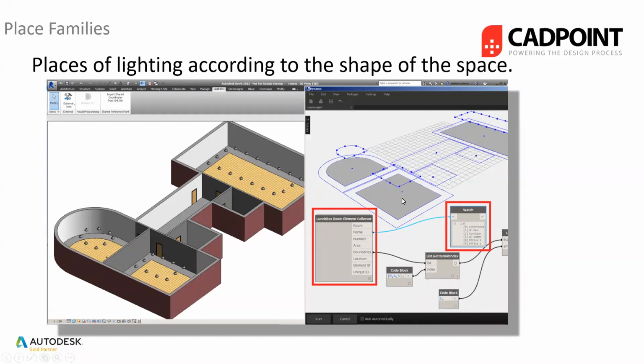And essentially what this script is doing, it's finding the boundary of the floor, it's offsetting it in by a meter, it's then coming up by whatever your ceiling height is, if it's 2.5 or 3 meters, and then it's offsetting in again by a certain distance, probably a meter, and then it's placing a point along each of those lines. It's divided each line, come along each line into the center, it's placed 4 along these. And each of those lines, then when you hit run on that script, you can choose what family to place at those points. So in this case, they've used a light family.